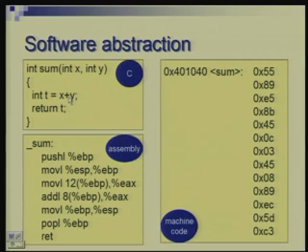Basically, what you see as addition here is this add instruction. There are some move instructions which you see above this add and below, which are essentially preparing the data before addition can be done. They are putting the data in the right place from where the circuitry inside a processor can perform addition. And the first and the last statements here are essentially required to actually link this function to a main program where this could be used.